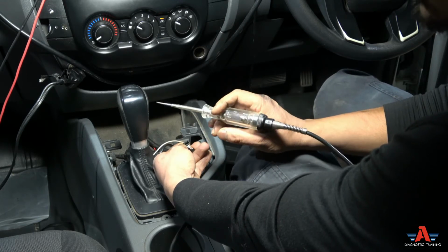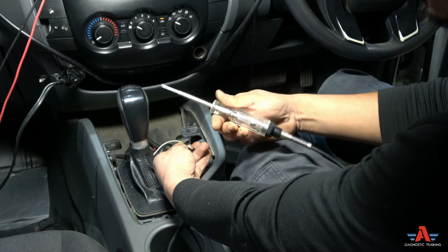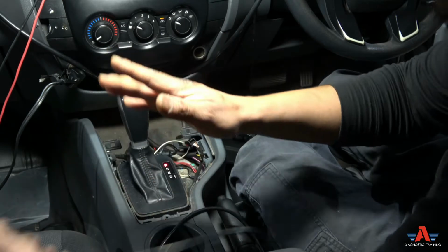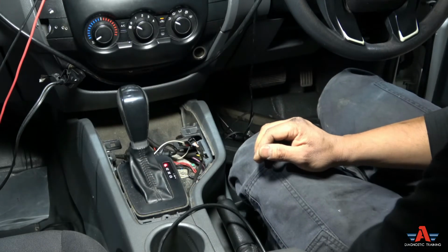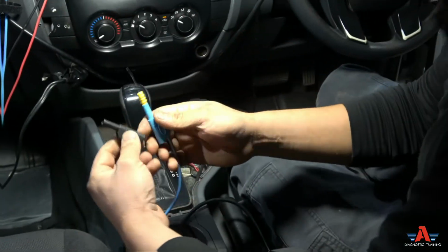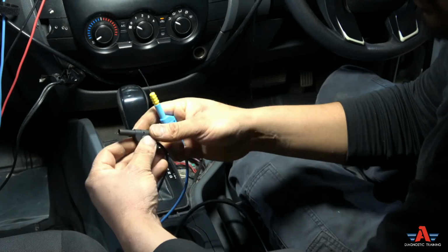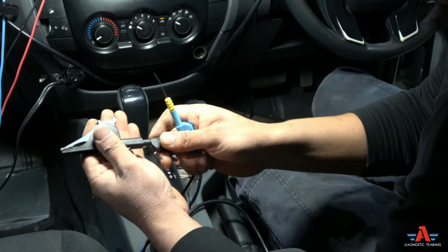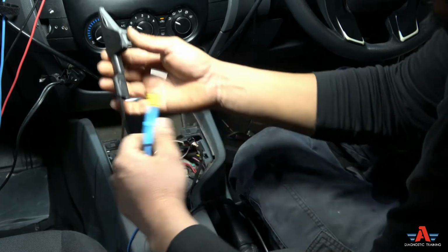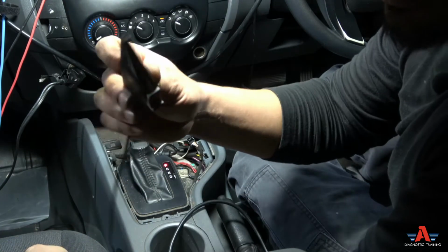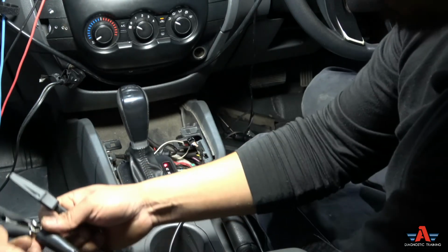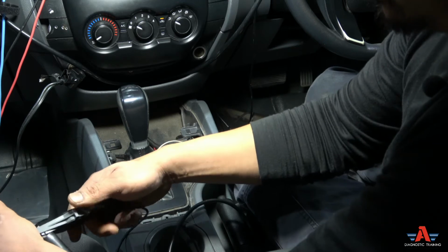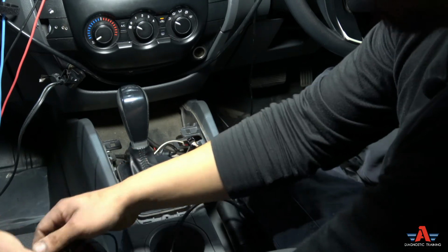If it's 5 volts, this test light is not going to light up because it only supports 6 to 24 volts. Okay, guys. For that reason, we're going to have to connect a scope. My scope lead here is connected to channel A. I'm just going to find the alligator clip and put that onto the battery ground. In this case, we've got this setup here. All right, I'm just going to connect that to battery ground.